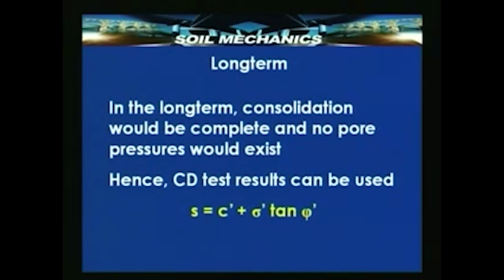On the other hand, the long term behavior, as I have mentioned already, is a situation where the construction is complete, the pore pressures have been totally dissipated, the dam is now in a condition which can be equated to the totally drained condition, that is consolidated drained, and the CD test results again can be used as we did for construction period where slow construction was permitted. s is equal to c' plus sigma' tan phi'.